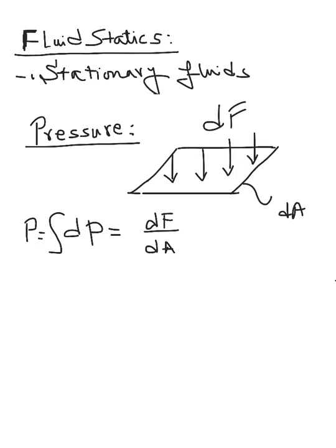Pressure is nothing but the force divided by the area onto which that force is acting. So if this is my elemental area onto which the force vector is acting, make sure the force is normal to the surface. This is a normal plane, 90-degree angle, and if the force is normal to the surface, the force divided by the area will provide you the pressure distribution.